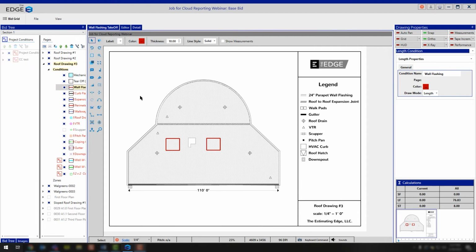Another essential tool that you have the ability to use is your gray non-current. This is going to toggle on or off depending on what you select, but when you left click on it, it's going to show you all of your conditions' colors, so that way you can verify and make sure that you didn't miss anything. If you would only like to see the current condition you're working on, simply left click on it again. When it does not have the little box around it, that's when you can tell that you're not going to be seeing all of the colors. In this case, you're only seeing the colors for the condition you're selected on, and it's graying everything else out for you.